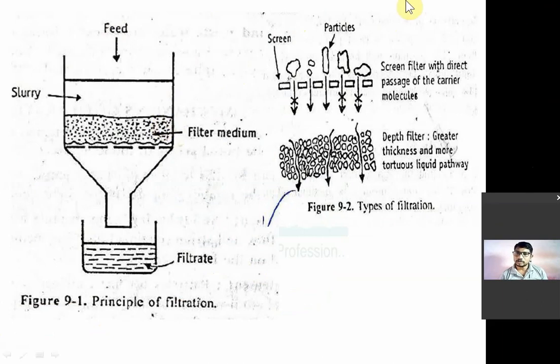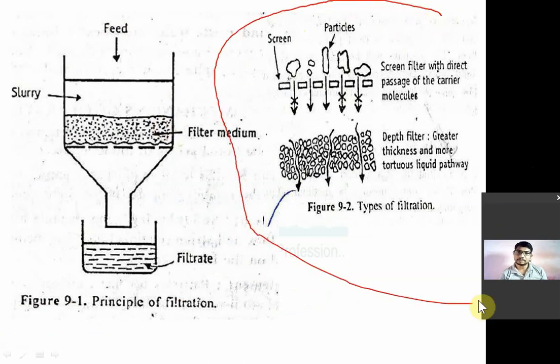Okay, so because of these perforations, your solid particles will not get entry, and they will be collected on the screen, and liquid will be passed. Liquid will be allowed. So screen filter with the direct passage of the carrier molecule. So that is nothing but the screen filtration or surface filtration.